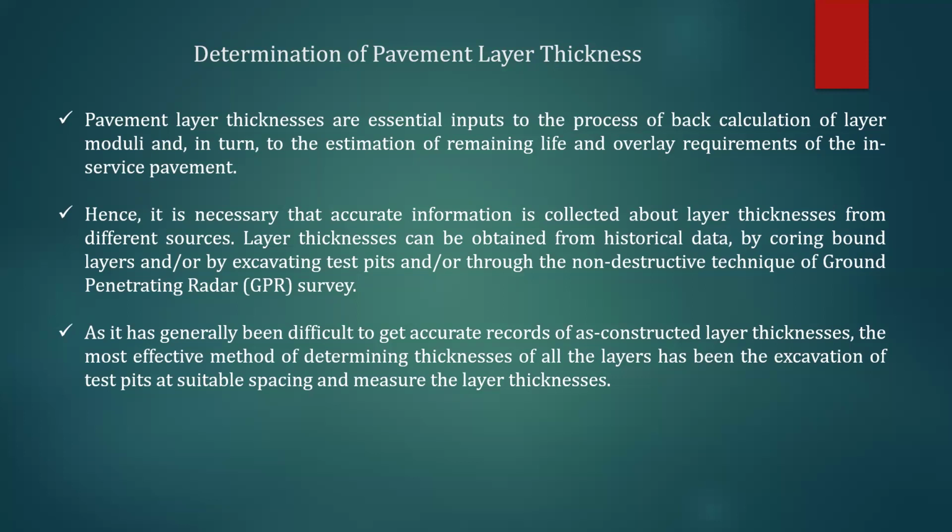Nowadays non-destructive techniques are also available, like GPR, ground penetrating radar survey, and so on. However, to accurately record all constructed layer thicknesses, the most effective method of determining thickness is excavation of the test pit. So the test pit is a very common procedure adopted to understand what the different layers are and what thicknesses are there.